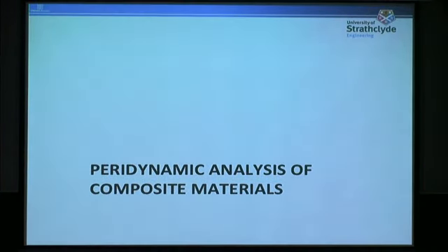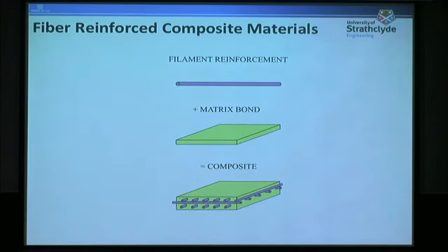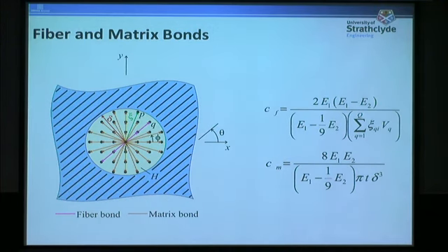So far, the material that I just presented is an isotropic material, but actually this is a very general formulation, so you can model any type of material. Just to give you an idea, I will briefly show how we can model, for example, a composite material, because it's an anisotropic type of material. Since we have fibers and matrices, the fiber direction is the strong direction. Whenever you have a new material behavior, you need to come up with a new material model.